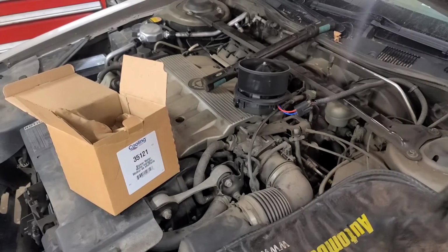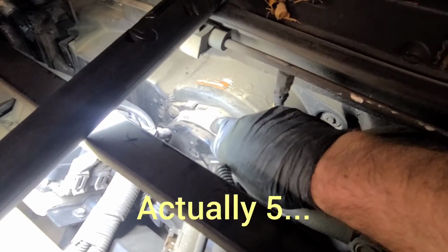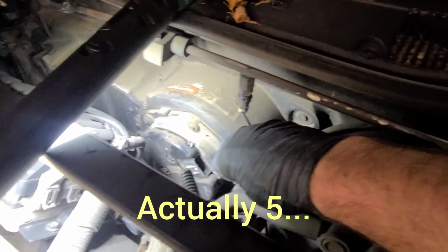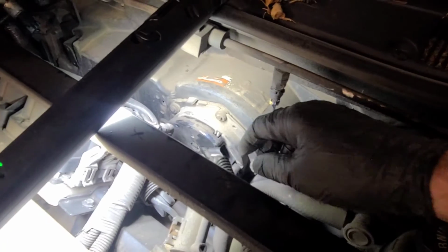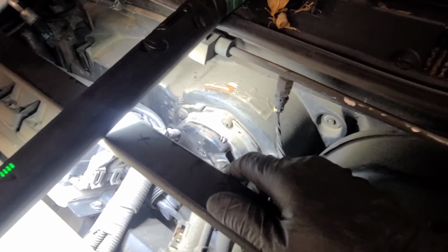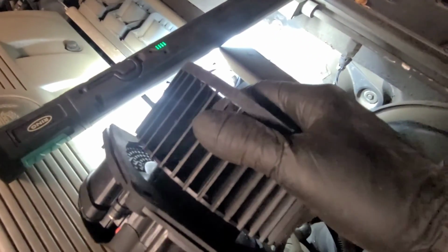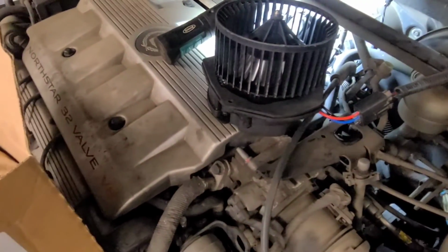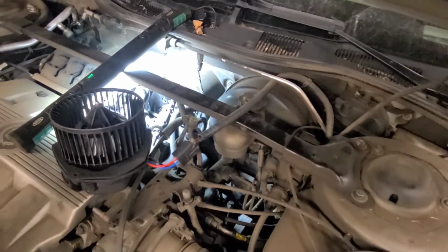Well, it obviously works, so we're going to install it now. So there are 4 mounting screws that hold the blower resistor or the blower motor into the housing. 3 of them are accessible. One is down there, I think. I think we might have to take the coil pack out of the way to get it out of there. It's fairly snug, but it only has to come out about 4 inches to clear. Might take this reinforcing bar out of the way here too. There's just 4 bolts. Or 4 nuts.